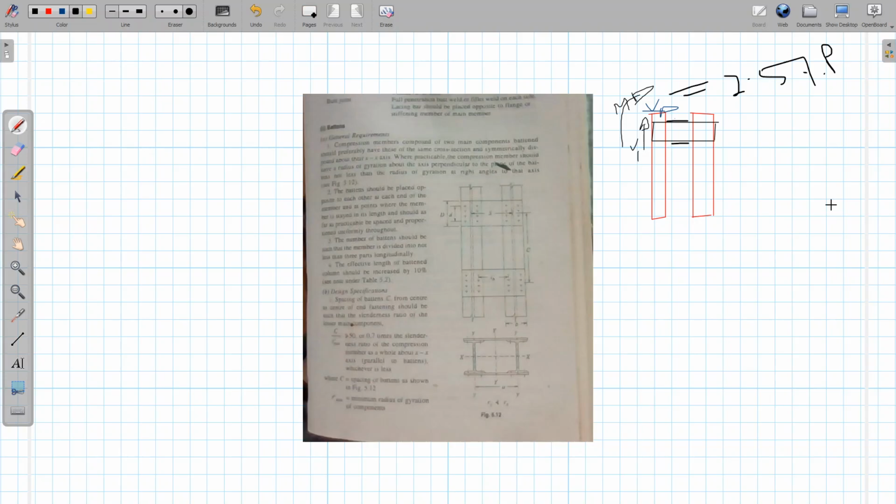One component is the longitudinal shear, which I have shown here as V1, and another component is the moment. And there are two planes in this batten, so this V will be divided into these two planes, 50% on the top plane and 50% on the bottom plane. So based on that we can calculate the longitudinal shear V1 as per the Codal guidelines.